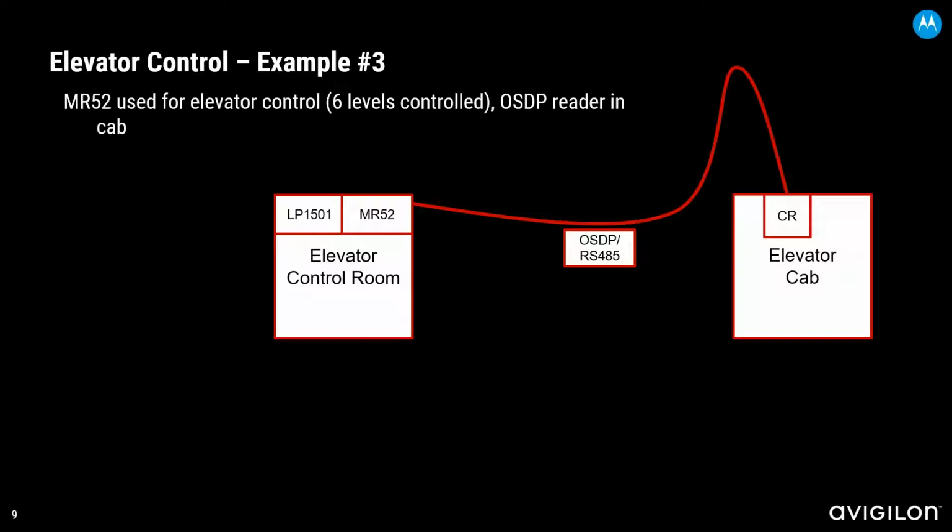Along with that, talk to them about the available conductors in the traveling cable. You want to make sure that you've got cables that meet your minimum standards. The only way you're going to know that is if you talk to the elevator control company ahead of time.